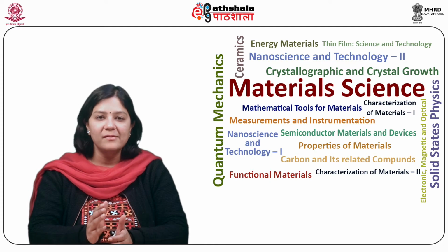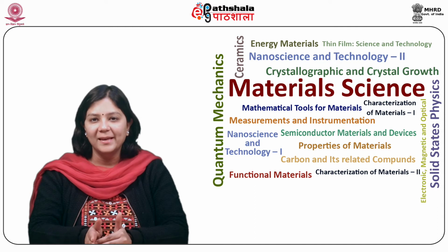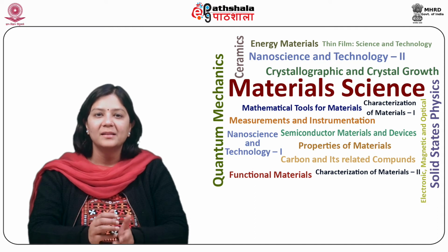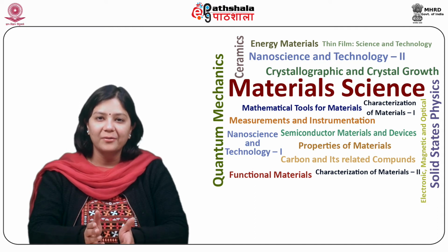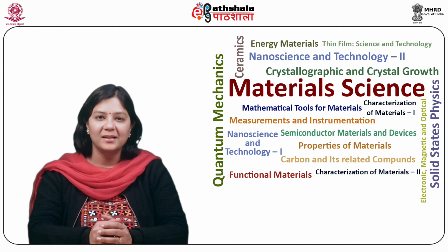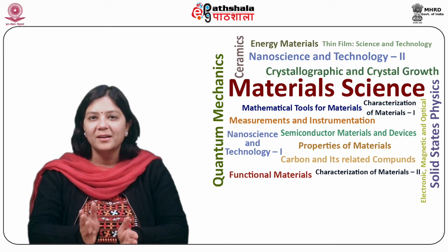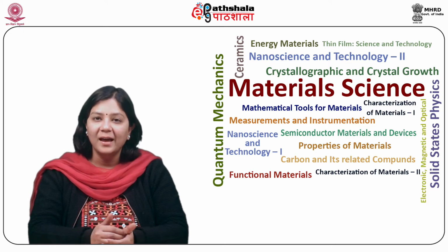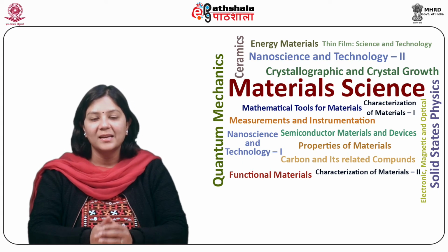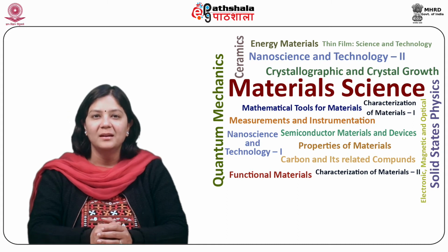It is different from MBE or molecular beam epitaxy in the fact that the crystals are grown via chemical reactions and not physically deposited. The process does not occur in vacuum. Rather, a gas phase is introduced inside the reaction chamber at moderate pressure of 10 to 760 torr.